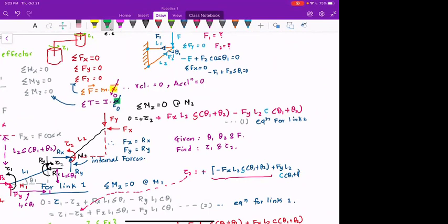So you will have some non-zero linear accelerations and angular accelerations. What it means is, in the worst possible scenario, the inertial effects are going to require more torques. So the inertia of the robot will require you to apply more torques.